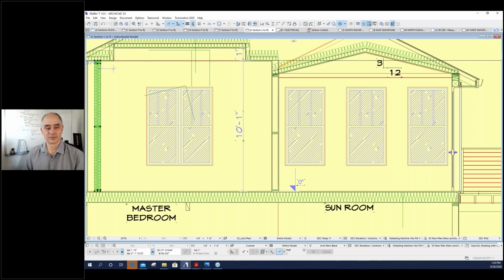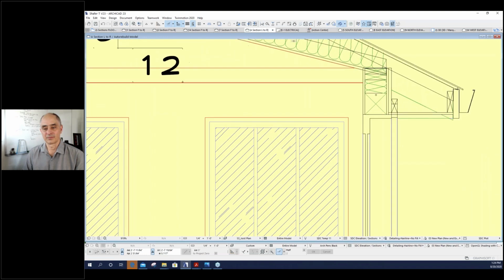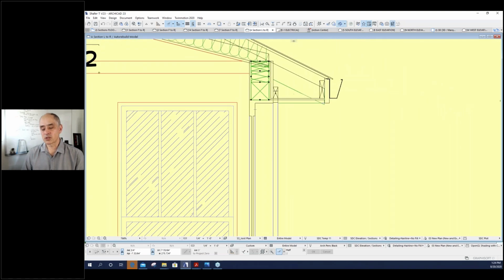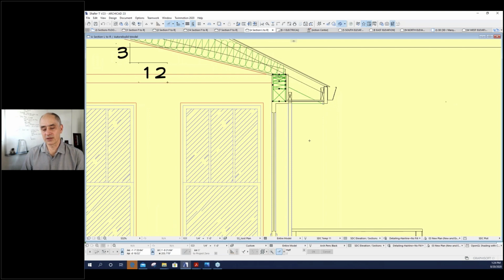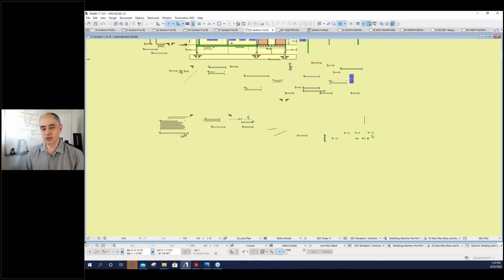You can adjust it to the wall, and it's a real good 2D tool. Here's the same with the insulation turned off, and then here's where the bottom plate is a header, and you can adjust that header size with the structural information. Okay, so that's smart. I would call that smart 2D in the sense that it's parametric. You're determining what components are visible, etc.